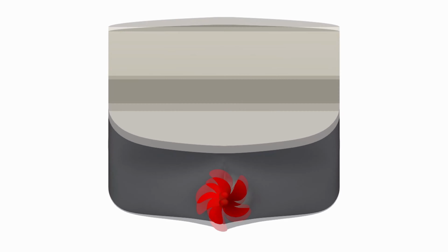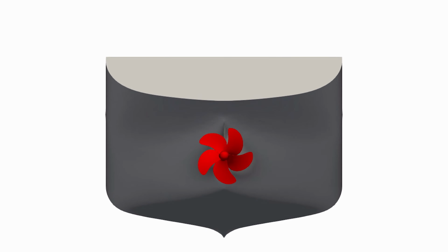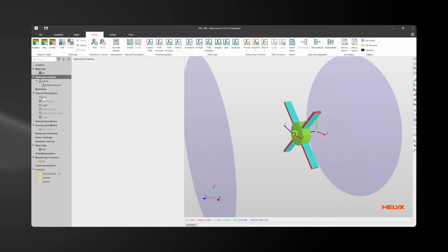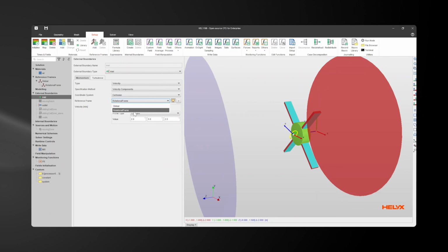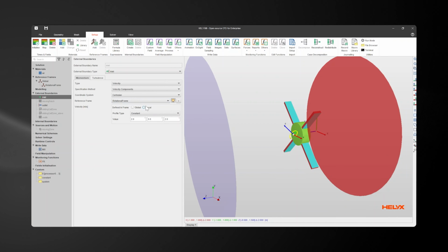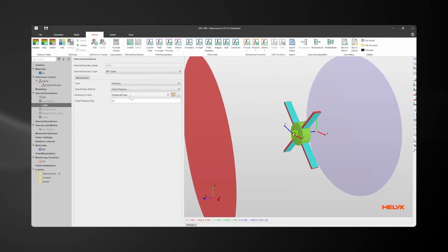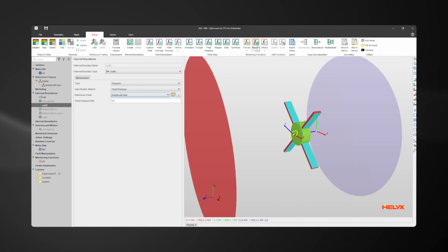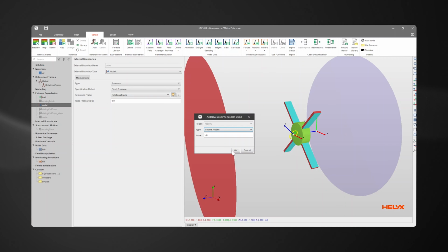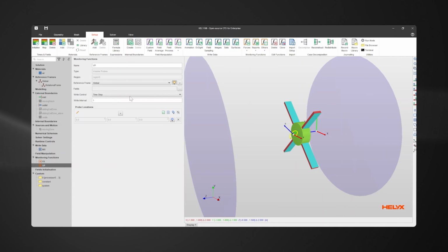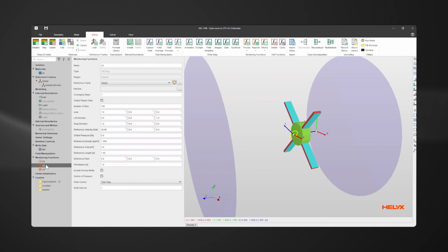Also in the previous versions, we introduced the concept of reference frames, allowing the user to set up local coordinate systems for some methods in HELYX and ELEMENTS. In version 4.3.0, we completely refactored the mesh motion library, and now the user can make use of local reference frames for nearly any feature available in HELYX and ELEMENTS, from pre-processing to post-processing. In addition to that, multiple motion frames can be combined into the same model, allowing an easy setup of quite complex simulations in terms of motion.